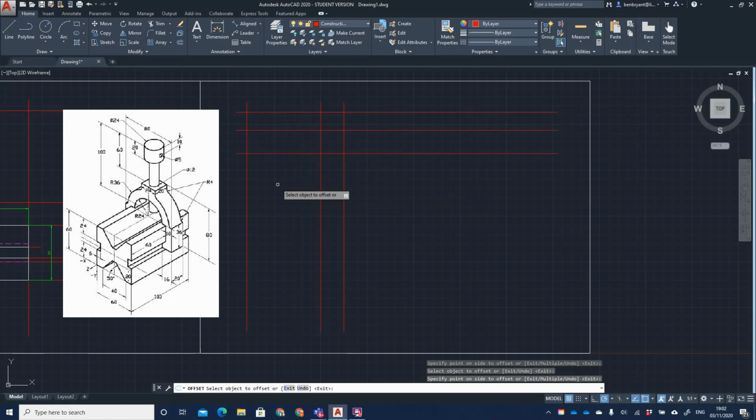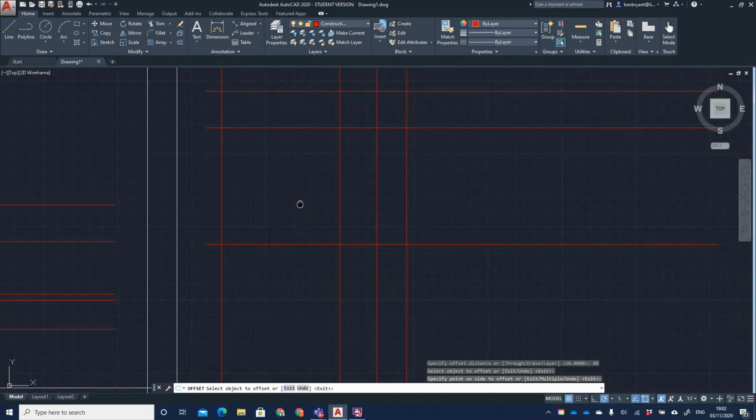So I'm going to do a top view, front view, and then there'll be a side. And again, the side is still going to be another 20mm, so I can put that back in, just using escape space every time. This time the top is going to be 80mm. Going to drop down. So I've got my top view up here, my front view in here, my side view there. So I've got all 3 designated spaces ready to go.